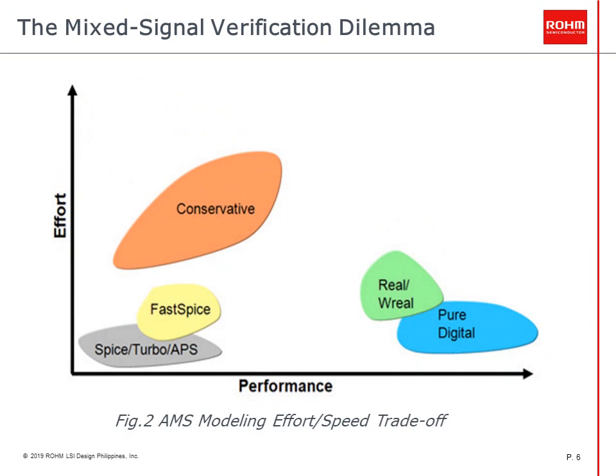Also important is the modeling effort shown in Figure 2. Here we can see that conservative models require the most amount of effort. You can potentially spend days, weeks, months to develop good behavioral models. Wreal models are relatively fast to develop because they're less detailed. An important rule of thumb: model what you need, not what you can.